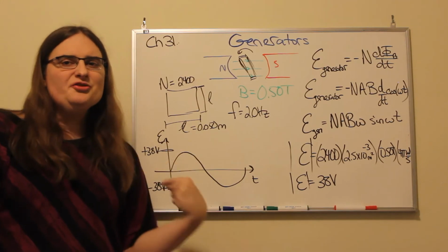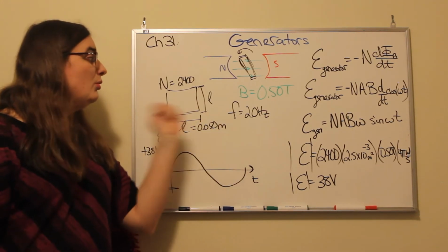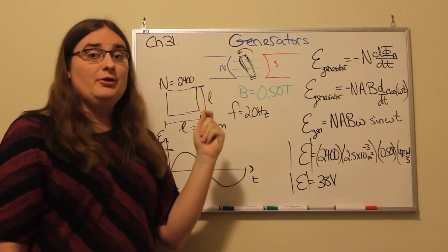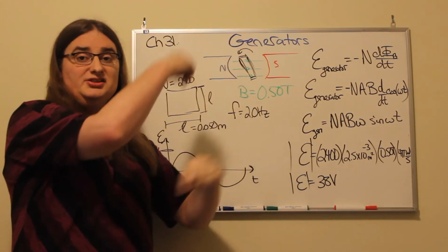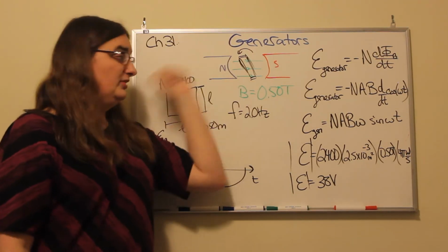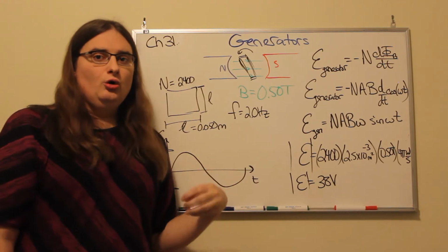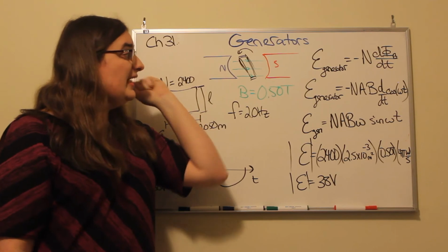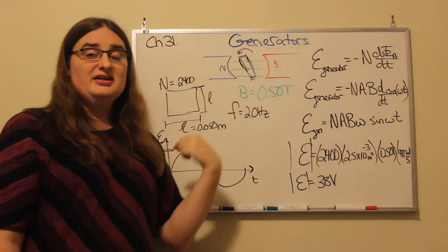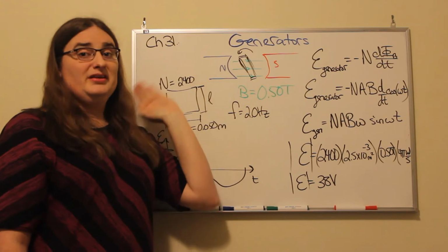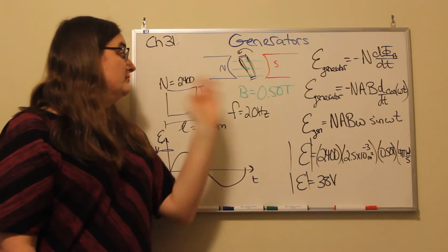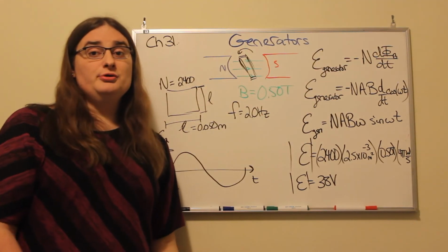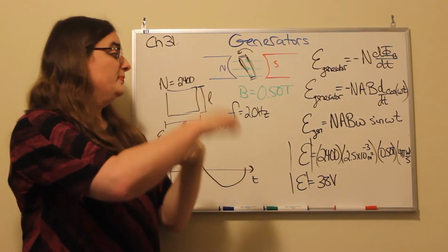Now, when we talk about different types of electrical energy, what we're really talking about is what we're using to spin a generator. So with wind power, the wind blows past fan blades, the fan blades turn, spinning a generator. With coal or natural gas or even nuclear power, what is happening is that fuel is being expended to heat up water. That water is then boiled, becomes steam. High pressure, high temperature steam gets pushed through a turbine, which is a type of fan, spins a generator, we get electrical energy.